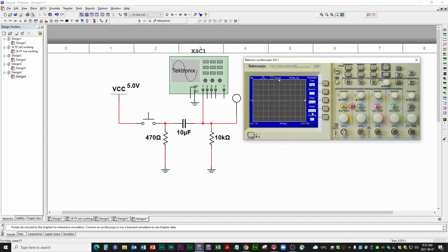So we have the trigger normal. Then the next thing, we're going to select the beginning of the sequence, not the middle of the screen. We want the scope to register somewhere at the beginning of the display. So here is the position for the trigger. Is that it? Yeah, there we go. And you just bring it right there.